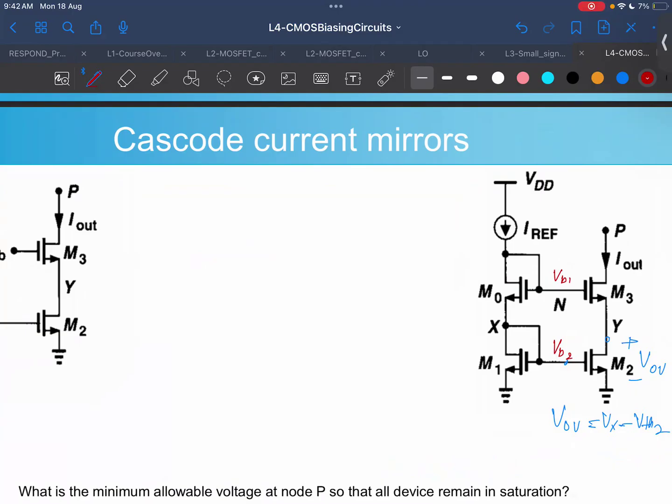So now, if we see what is happening, the question which we were having was, this is good that you can minimize the error, but what is the downside of this architecture, right? And clearly, when somebody looks at multiple transistors on top of each other, you see the headroom, or the swing, which we will talk about also in amplifiers, is quite reduced.